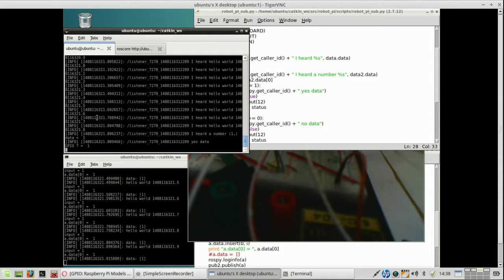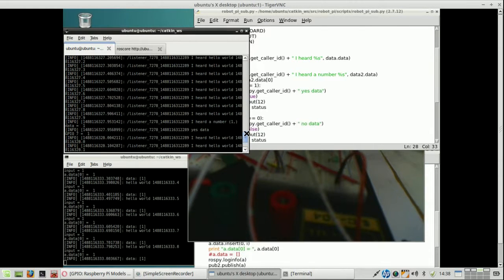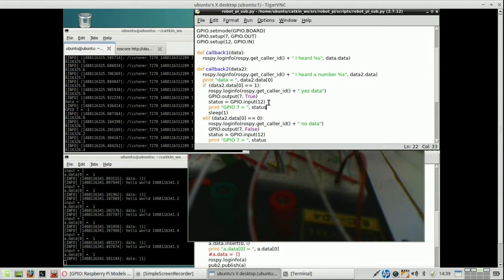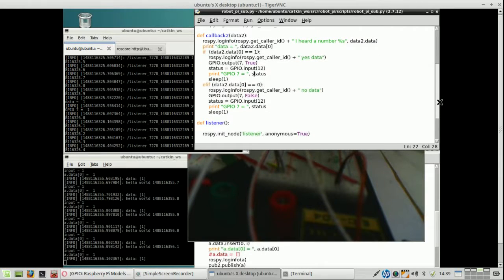And it says, oh, that's a little bit difficult now, because now I have to read here and here, and that's not easy. So let's see, wherever I see here it says GPIO is 1, but GPIO can only be 1 when I press the switch, or should be only 1, and that is not the case. So here we already have a problem.